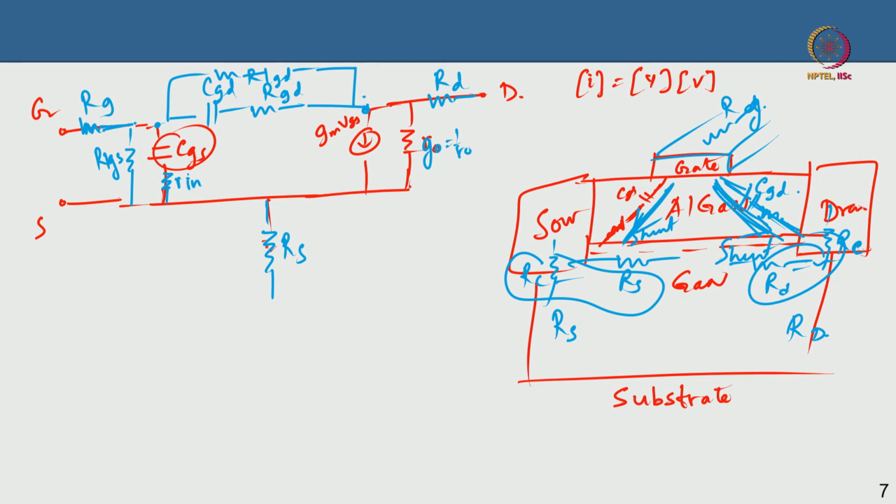Now the drain and the source, when you have depleted this in the off state, for instance, might capacitively couple to each other. The source and the drain through the buffer might capacitively couple. So I have to give another capacitance called CDS, the drain source coupling capacitance. This could be through the depleted area, and through the buffer there could be coupling. If the buffer is leaky, then this becomes a problem. So that's the drain to source capacitive coupling.